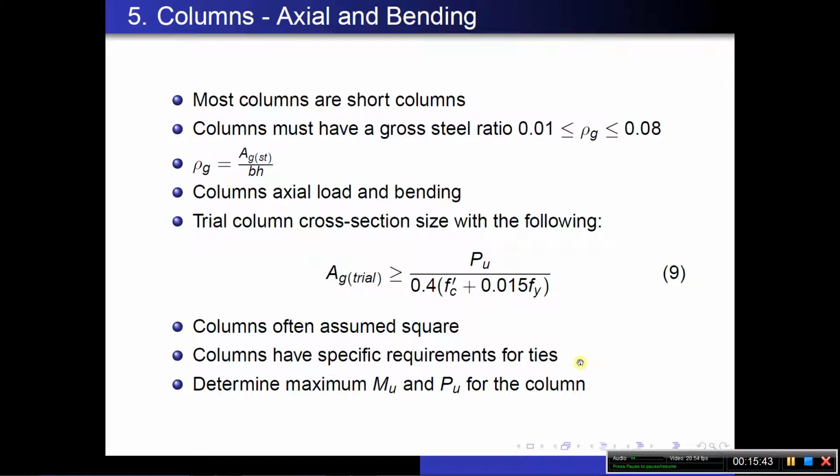Now, the other thing that you will have in your columns, besides the steel that is along the length of the column, is you will have what are called ties in the column cross-section. And they will look very similar to stirrups that you saw in the cross-section of a beam. For whatever reason, in concrete design with columns, they tend to call them ties instead of stirrups.